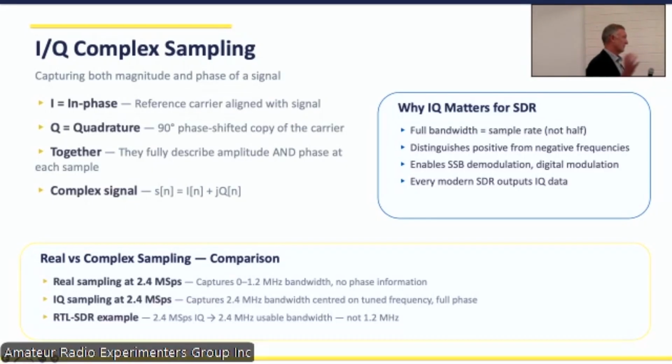It's the same issue with Nyquist. It's always twice plus a little bit. It's the same with IQ. The part that you're also going to remember is there's two components. So the total amount of data that we get out of IQ is the same as real. But it is mathematically easier to calculate with and to work out, especially our complicated communications, like what we use in 5G, 4G infrastructure. But even for FM, most of your information is sitting in your quadrature. So being able to very easily take that information out is the advantage of IQ.